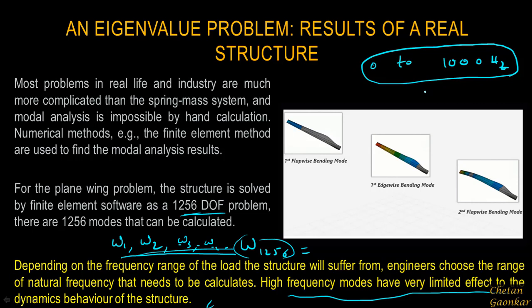First one should try to understand exactly what range of frequencies this structure will be subjected to, and then within that range one should extract all the modal frequencies, and accordingly study the mode shapes.